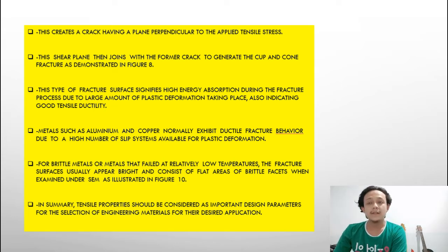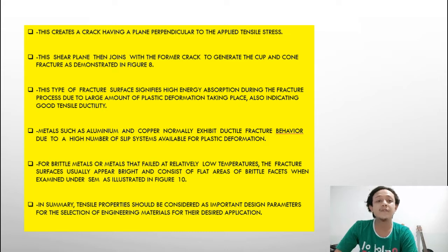For brittle metals or metals that fail at relatively low temperature, that fracture surface usually appears bright and consists of flat areas of brittle faces when examined under SEM, as illustrated in Figure 10. In summary, tensile properties should be considered as important design parameters for the selection of engineering materials for their design